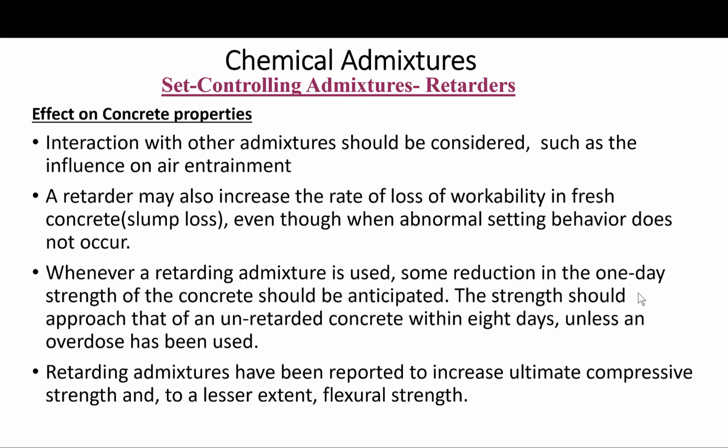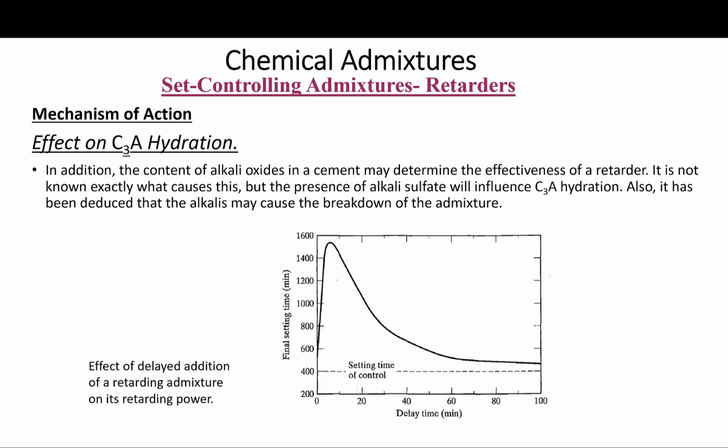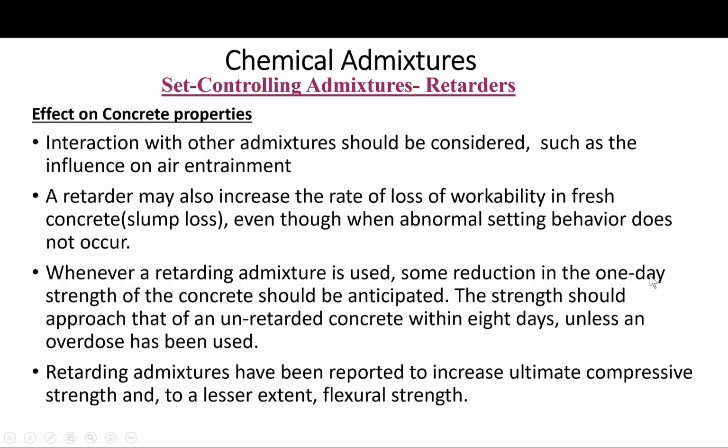Also, as mentioned earlier, retardation increases when the addition of a retarder to concrete is delayed a few minutes after the first addition of water. So retardation is increased rapidly up to about 10 minutes, depending on the admixture type and dose, and then slowly decreases as shown in this figure here, okay?